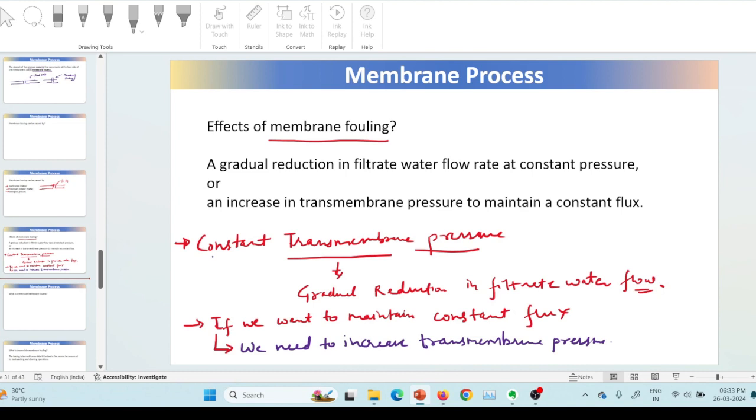If more head loss occurs, the discharge reduces, provided the head is constant, so the discharge decreases with time. So after a certain time, we do backwashing. Likewise, here also the same concept is used. So if the head loss increases, we clean it.